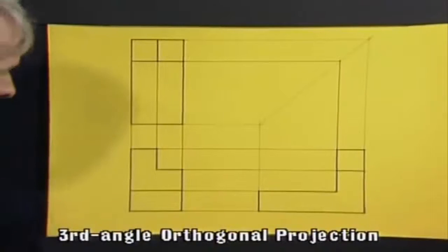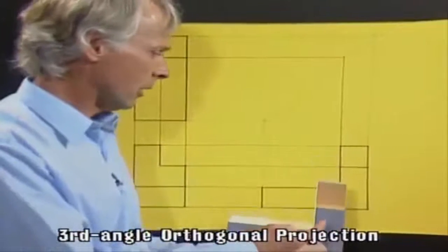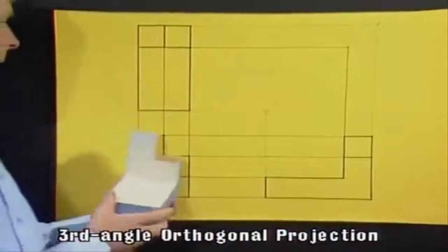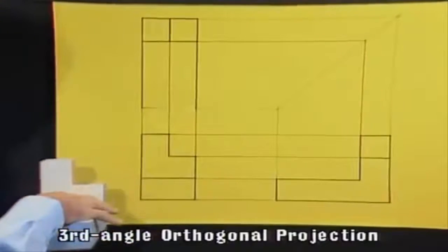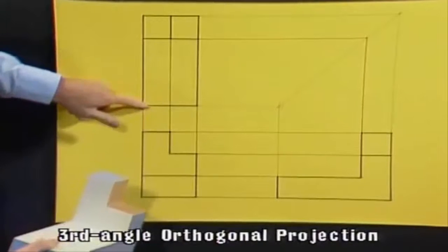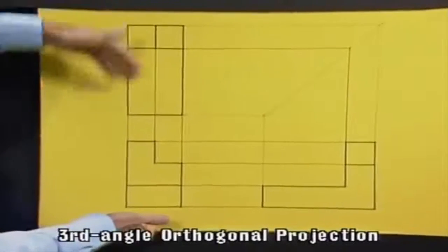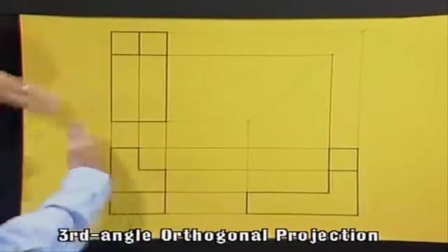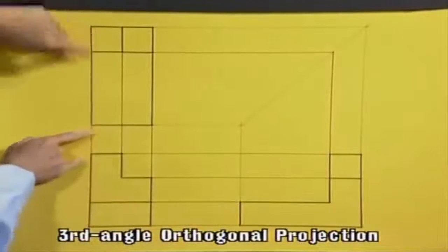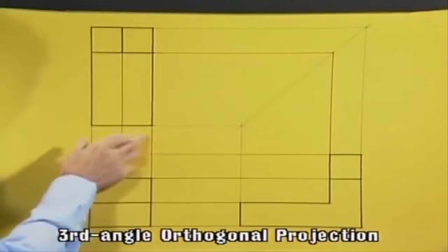I mentioned before about the choice of front elevation. The front elevation Boundy chose was that view. If we'd have chosen this view instead as the side view, we would end up with a very tall plan view, and this gives a lot of restriction in this space here. To get that all onto the page, pages tend to be fairly horizontal in layout. They're longer than they're tall. We've got a restriction here. It makes it difficult to insert much in the way of dimensioning into that space.